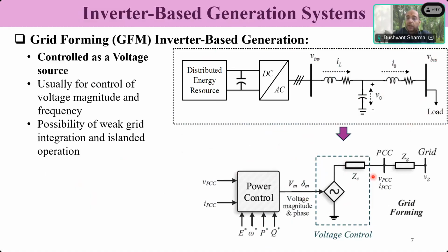So now the control mechanism will completely change, and the same inverter will behave like a voltage source. That means it is controlling its own frequency and phase angle, Vm sin(omega t plus phi). All the three variables, Vm, omega, phi, are variable. There is no grid, so it can produce its own frequency, its own voltage,